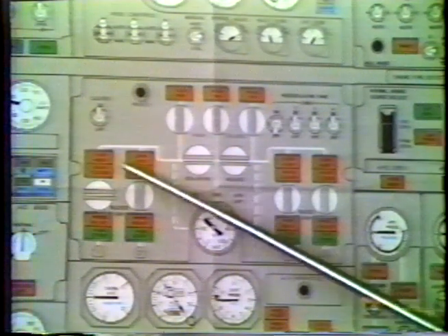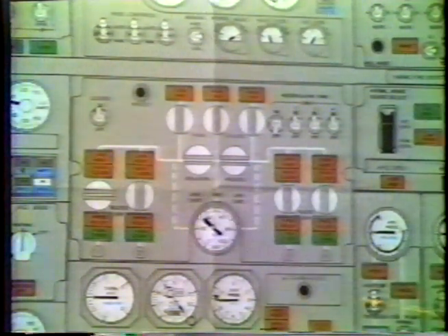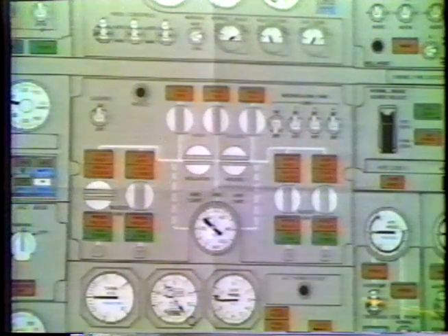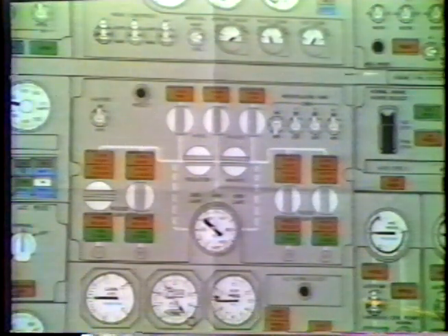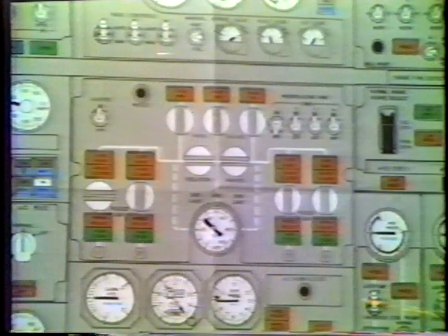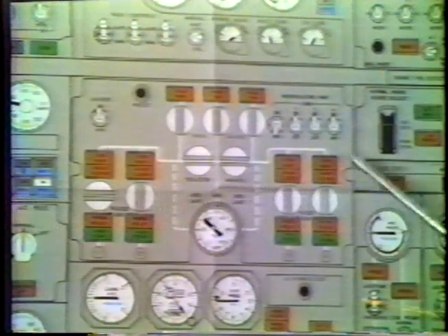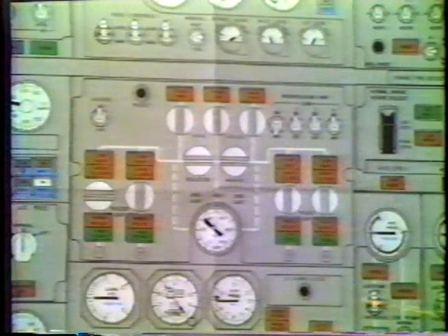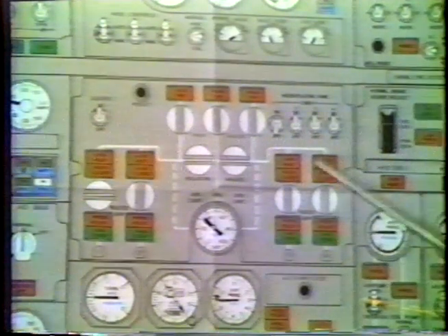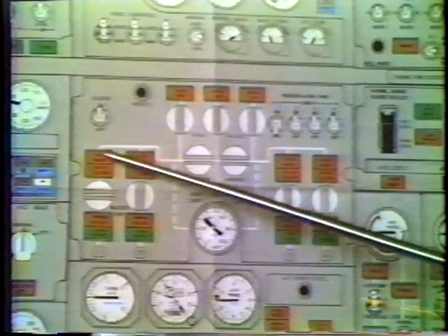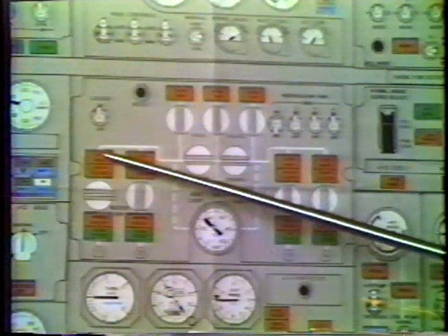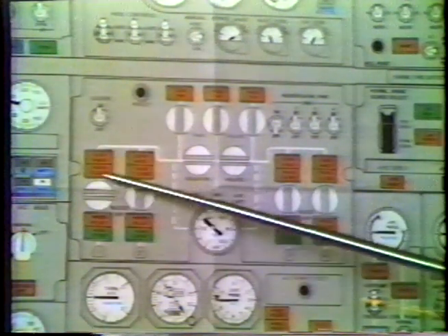There is an overheat light above the valve close light, which very seldom would operate. As a matter of fact, for this overheat light to operate, it would take a dual or triple failure. On some aircraft, the overheat light has been omitted from the airplane. What it indicates is the temperature of the air downstream is excessive, and it would close the valve.